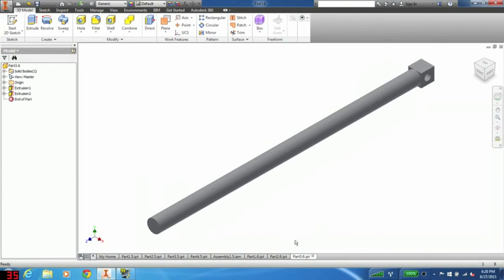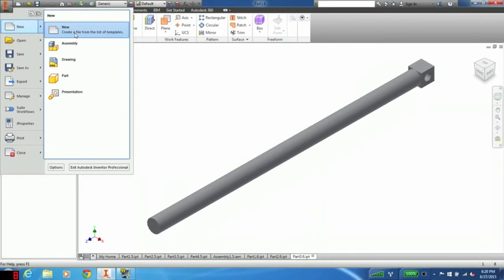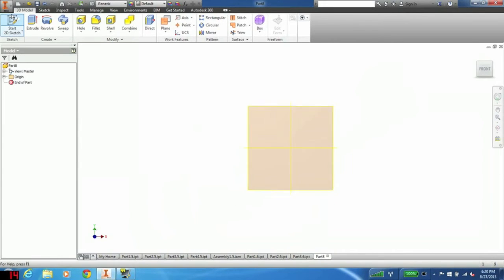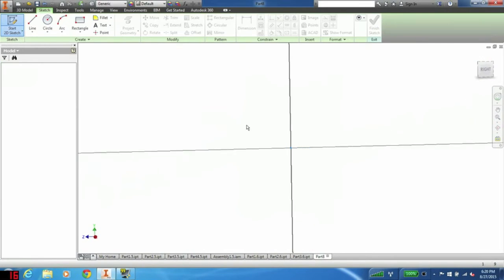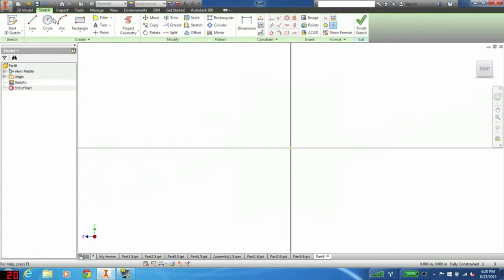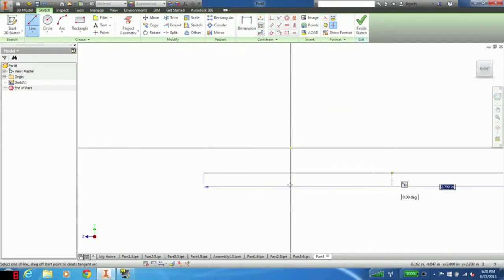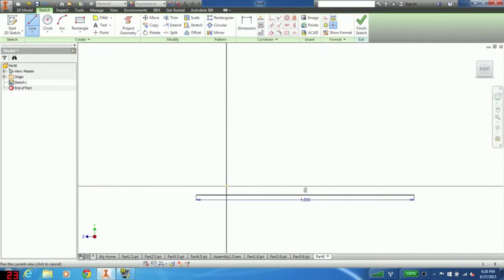So we're going to create one last new part. And we're going to again put this on the YZ plane. And we are going to start with base, which will be 4 inches as a horizontal line. And then let's zoom so we can see it. And then for that cube, the flat part of the base is 1/8 of an inch in height, and then the cube that the cylinder goes through sticks up another 1/2 inch, so we can add that together to get 0.625.